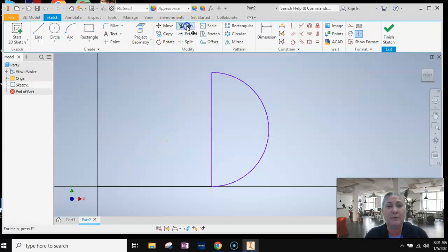The trim tool is up here. I'm going to left click it, up center. I'm going to come down here, and even though it doesn't look like a line, we have a line on top of the x-axis. So let's left click it and hit delete on your keyboard. When you move over it, you'll see that nothing highlights anymore.